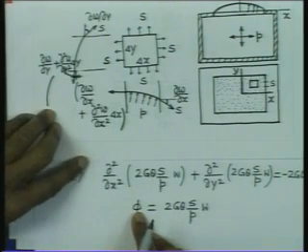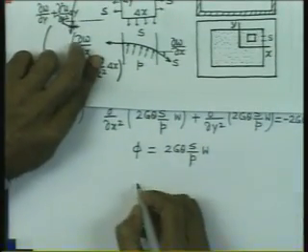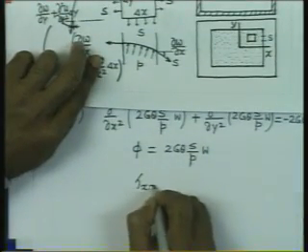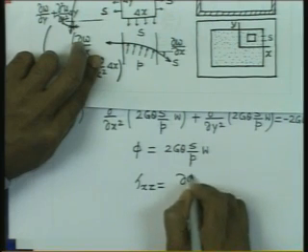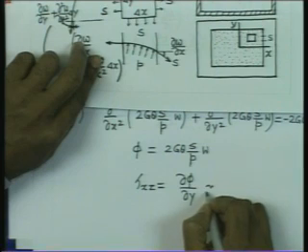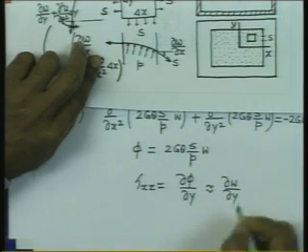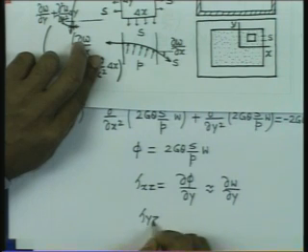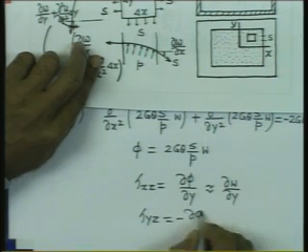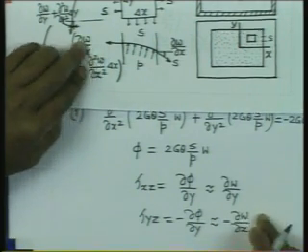In fact, the stress tau xz is given by ∂phi/∂y. So, therefore, it is also going to be related to ∂w/∂y. Similarly, tau yz is minus ∂phi/∂x. So, therefore, it is related to ∂w/∂x. So, membrane shape will give us the idea about the stress.